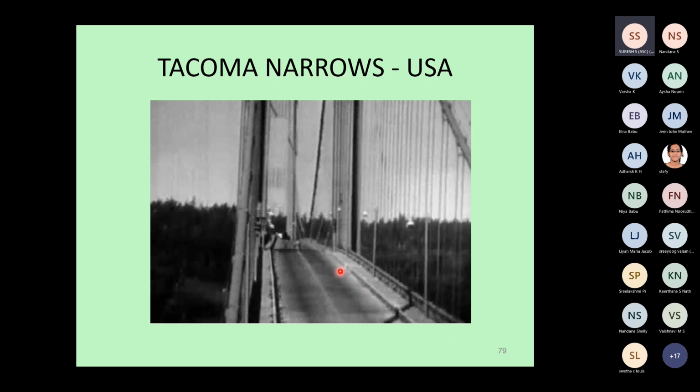Now you can see this is a bridge called Tacoma Narrows, a suspension bridge, of which this is a video. Probably you can search for this wording on the web and you will get this video. This is the only bridge that has been videographed during a real failure. This bridge was subjected to a normal loading, not an abnormal loading, no cyclones or anything, usual loading, and then started vibrating. And this aerodynamic flutter became a huge vibration, causing the final failure of the bridge into the river.